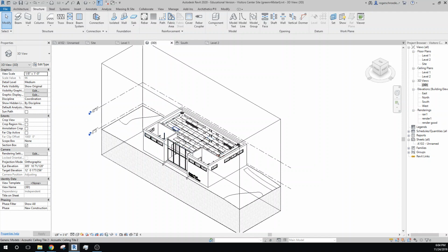And I'm going to put some trusses across here, some beams actually, to support the load of those. I'll put those 4 foot on center, and I'll let them span from the front of the building to the back. And that brings up a few structural issues that we haven't resolved, like how would we carry that load here, but we can address that later on.